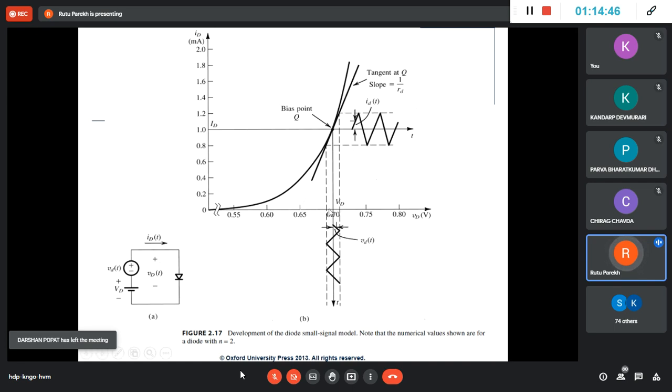That we have given a proper condition. I have a small signal, which is from some few millivolts, right? And if I want to process this, I have to make the diode on, because if I don't have this VD, this DC voltage, then this diode will remain off. Up to 0.7, it remains off; up to 0.5, 0.6 it is off only. So if my signal is small and I want to process it, it will remain dead. It cannot process. I have to make it on, and that is the simple definition of biasing.